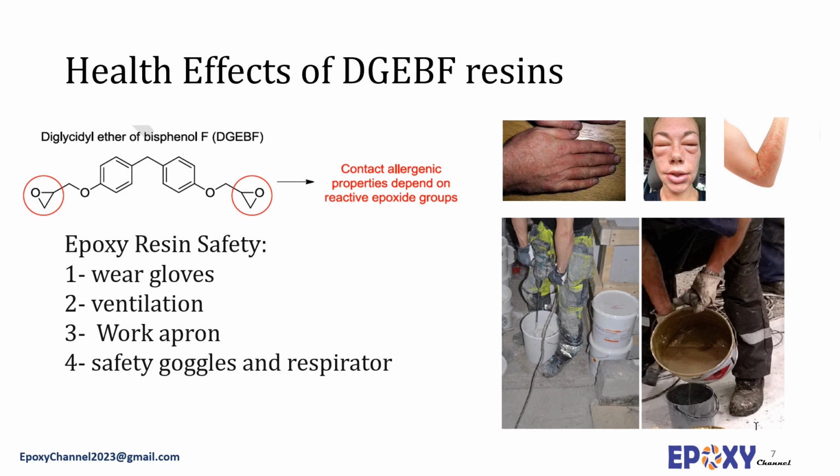In occupations with heavy exposure to uncured epoxy products, sensitization often occurs within a few months after entering the trade. Hand dermatitis is a common symptom, but facial symptoms are almost as common. The dermatitis usually heals if the exposure stops, but many patients need to change jobs. Generally, exposure to these epoxy materials should be minimized and avoided if feasible. When handling, through the observance of proper precautions, the worker should use appropriate engineering controls and proper personal protective clothing and equipment, and adhere to proper handling procedures, which are often provided in the SDS document.